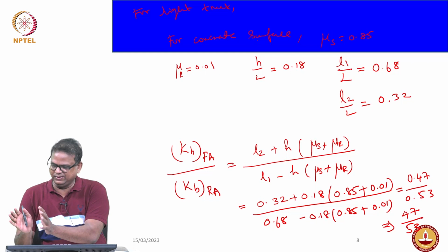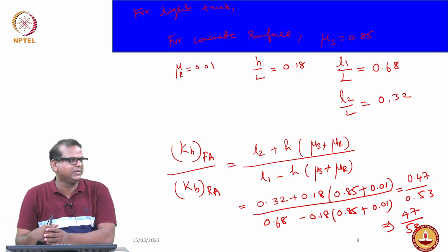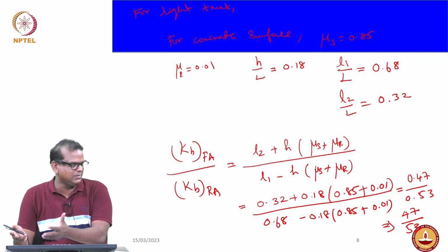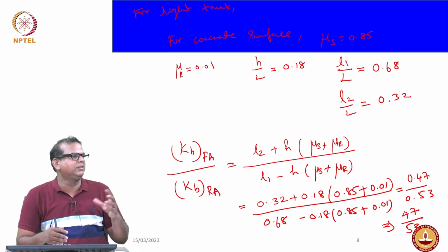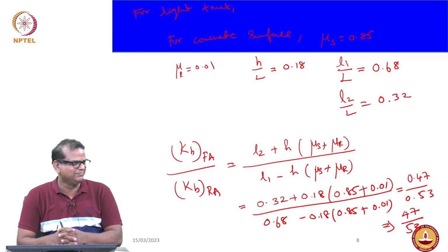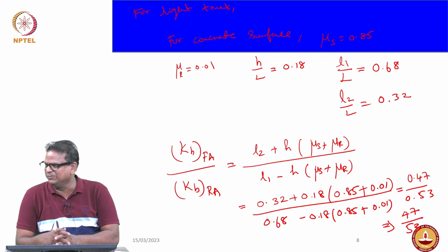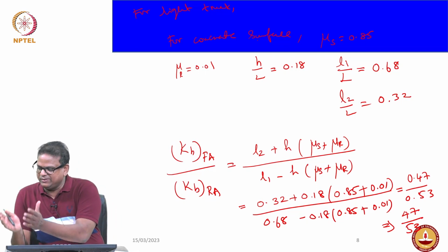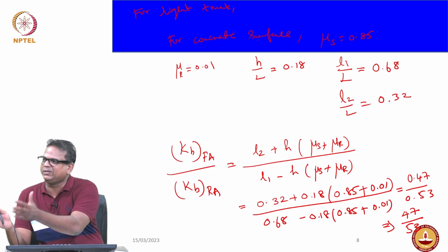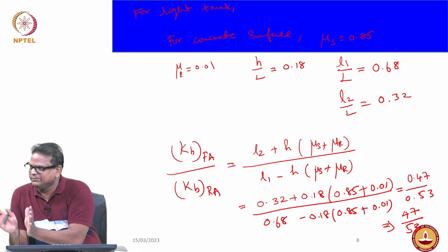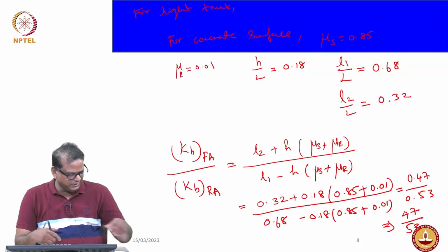So to meet the dynamics, we use different brake systems. For the rear we use the drum brake system, and for the front we use the disc brake system. So as long as you meet the proportion, how does it matter? Is it clear to you? Either the disc brake or the drum brake must be equivalent to whatever proportion you are getting. That's what you have to satisfy dynamically, right? So it doesn't matter whether you do it with the drum brake system or disc brake system.